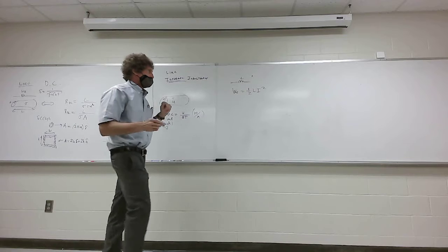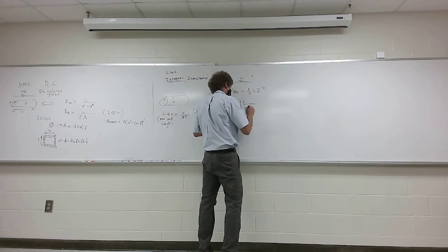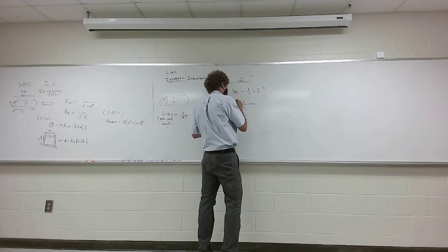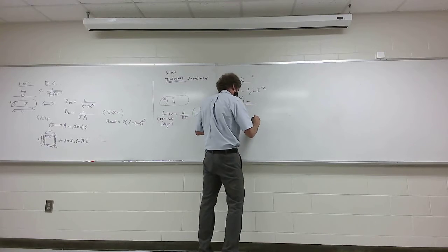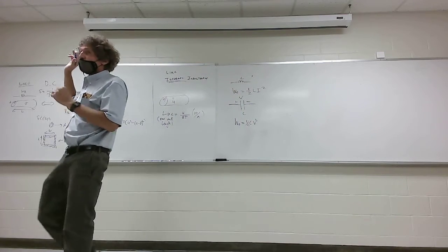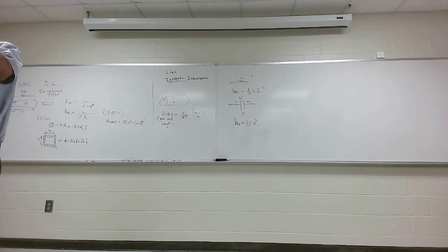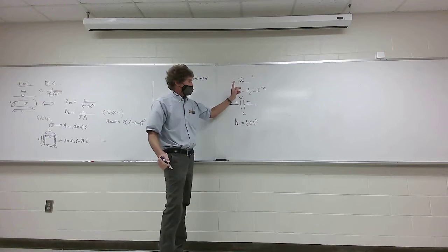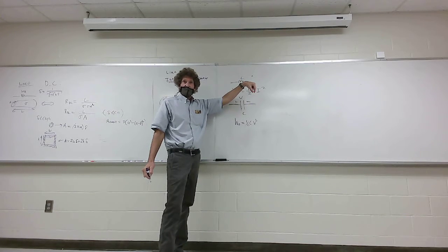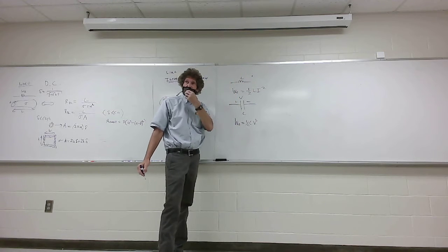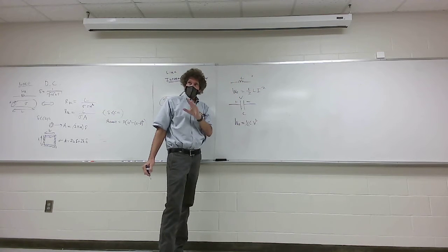Now, there's something else you should remember while I'm on this. If that's a capacitor, and there's a voltage across that capacitor, how many know the energy in the capacitor is 1/2 CV squared? Remember that? It's important you do, because that capacitive energy, the ability to store energy for a given voltage, is available, you can pull it out. With this current flowing through there, you can reroute that current through a resistor or an antenna, and all that energy is available to dissipate or propagate, either dissipate through the resistor or propagate from the radiation resistance. Y'all hear me on this, guys? So that's the reason you keep that in mind.